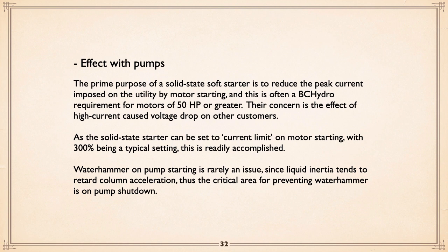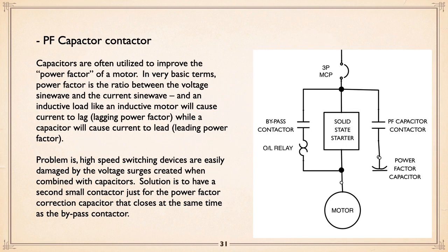Now, the ramp down, as I say, water hammer on pump starting is usually not an issue because the liquid in the lines acts to retard acceleration. So people say, oh, you turn the pump on, you're going to get a shock wave. Actually, it's really more of simply going to the shutoff head of the pump and then dissipating down from there. It's not that. But shutdown is a different ball game. And this is where, as I say, between mechanical and electrical, holistic is important.